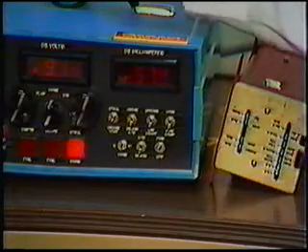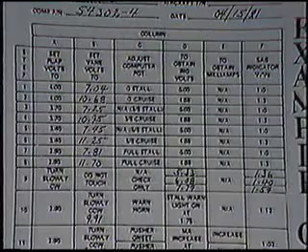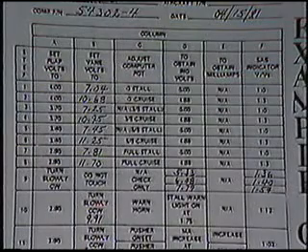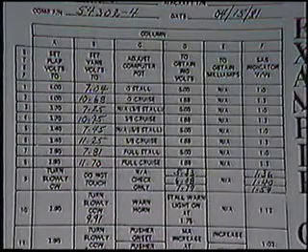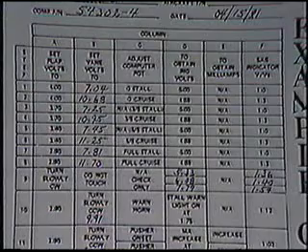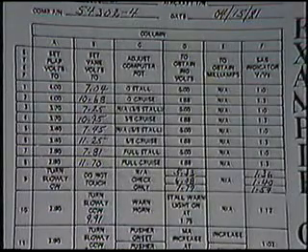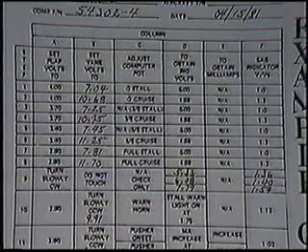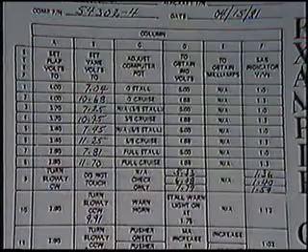The first item is to see that the computer is properly adjusted. This is accomplished using the tester and the aircraft's original setup numbers. Follow the step-by-step procedures listed in the manual. These procedures will set the computer to work with the actual numbers relevant to the aircraft involved. These numbers are contained on the SAS data sheet supplied with the aircraft.